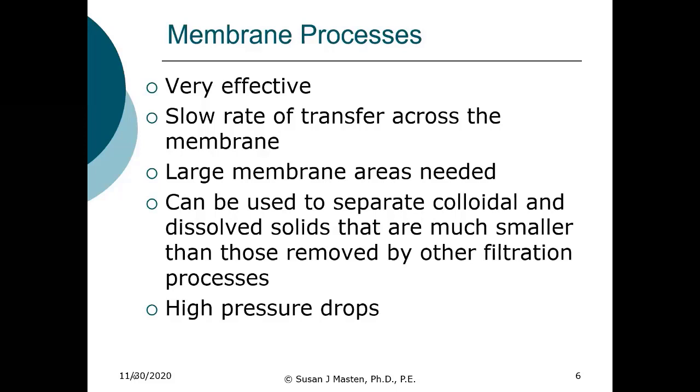Now, we can use this to separate colloidal and dissolved solids that we couldn't separate effectively by either sedimentation or by granular media filtration. The disadvantage is that there is a high pressure drop across the membrane surface, and that means that the system requires a high amount of energy input.